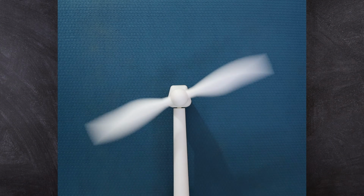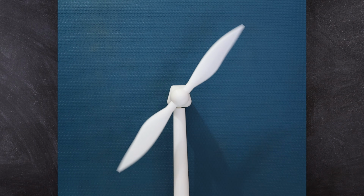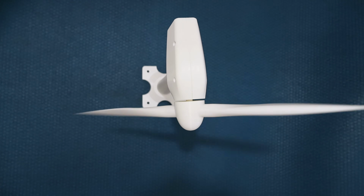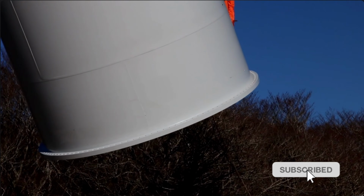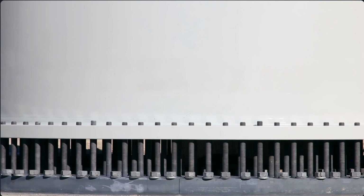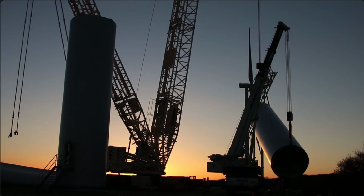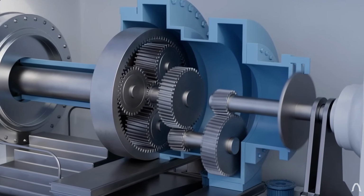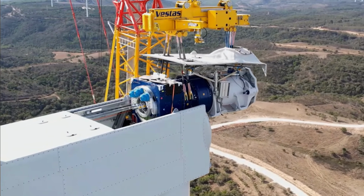You see, an even number of blades present a different kind of imbalance because of the unavoidable problem that one blade always opposes another. Stability and vibrations are inevitable. The structure has to be more robust and heavier to accommodate the vibrations. As a result of vibrations and instability, the lifetime of components such as bearings, gears, and other drivetrain components is significantly shorter, leading to more frequent downtimes.